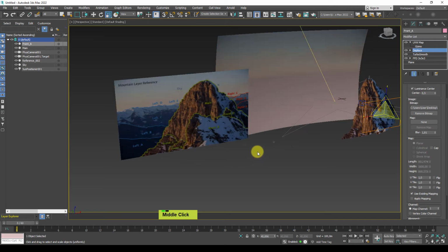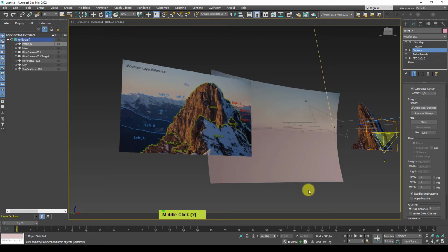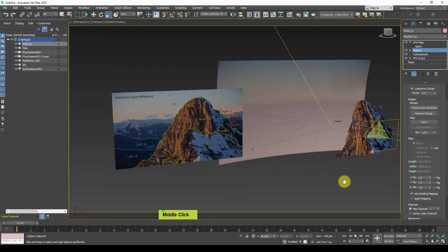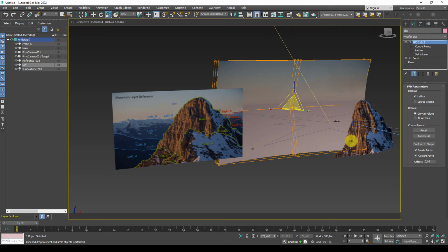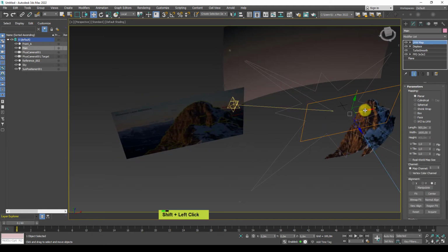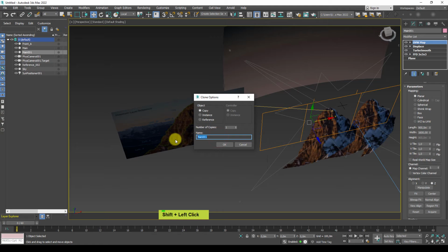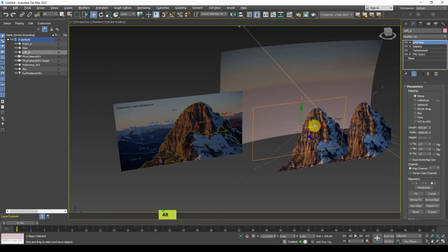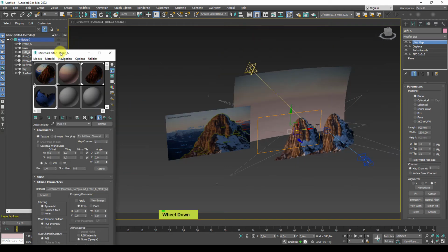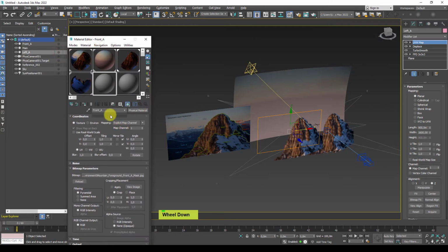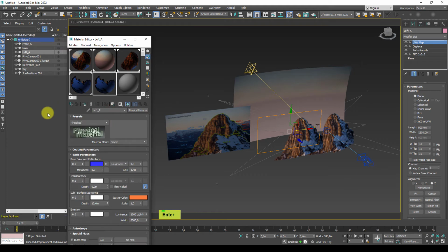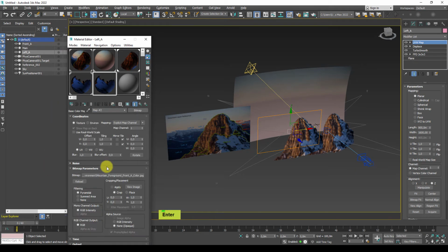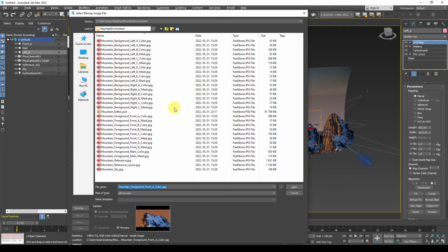Okay, so what's next? This was the first thing, but we can go with the left A, for example. Just quickly create a left A view, and I will set this and rename it to left A, just with the first panels. So there we are. Open up the Material Editor, drag and drop, copy. That will be left A, and the material should be left A, so left A color, and there you go. That's for left A color.